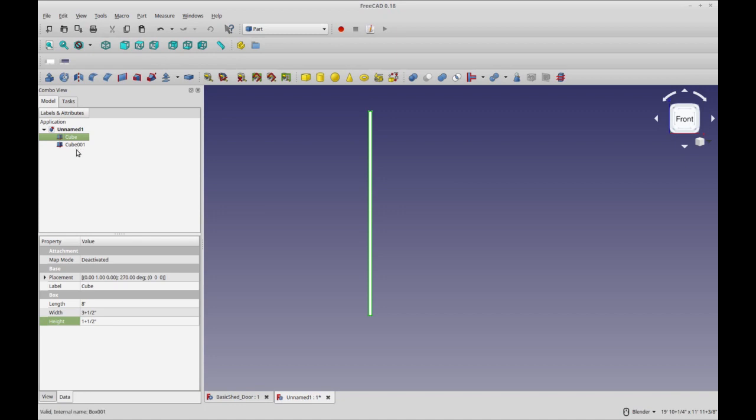So I'll have 1, 2, so these will be resized. Let's hide these for now, and let's resize this to make it fit in a standard wall opening. So that's going to be minus the bottom plate, and I'm going to do 2 top plates. So it's 1.5 times 3, which is 4.5 inches. So lumber in the United States, pre-cut studs are sold at this length, so that's why I'm doing that.